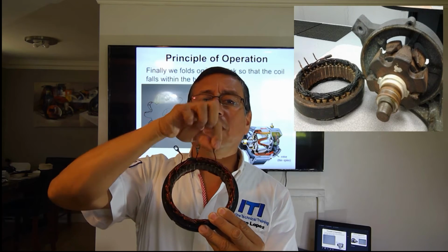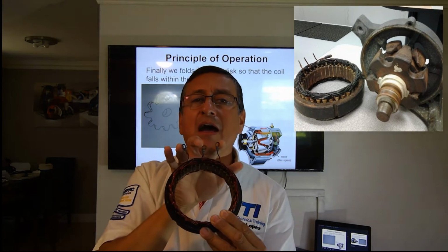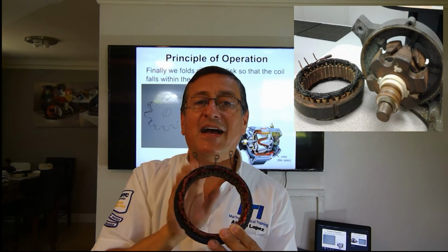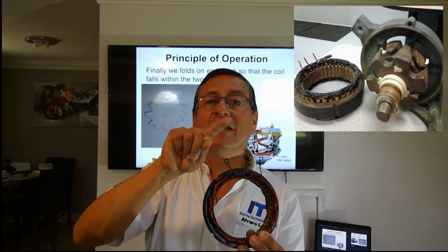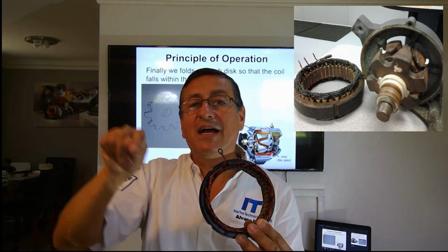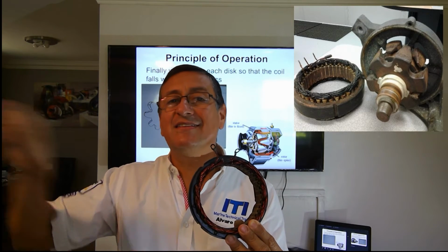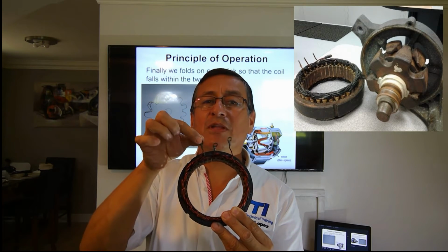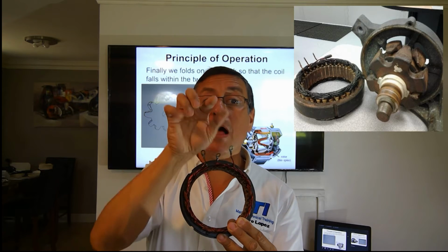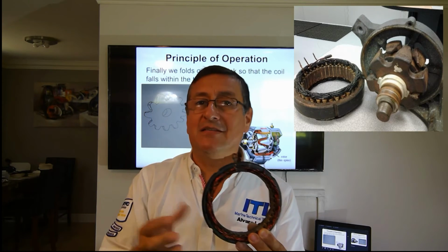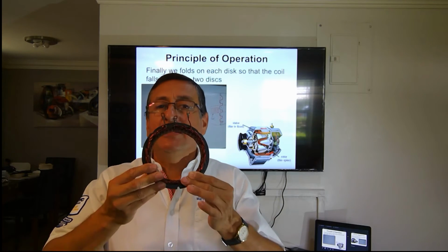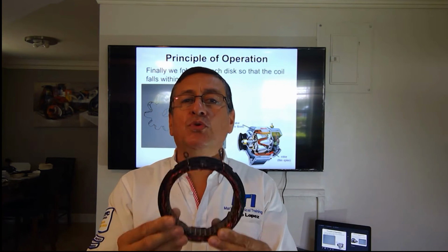If I connect a voltmeter between this end and this end, and the rotor is spinning at high speed, the voltmeter registers the voltage and the AC signal. Or if I connect a light bulb between this point and this point, when I move the rotor, the light bulb produces light, AC power. This is basically the simple way to produce AC current.